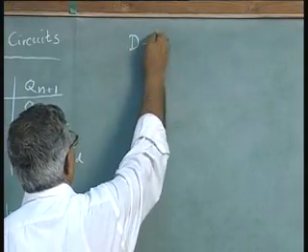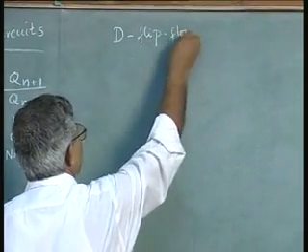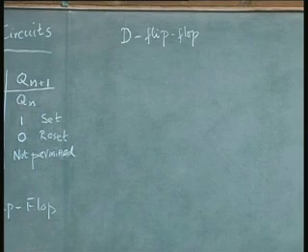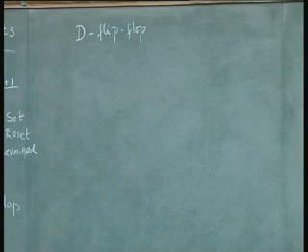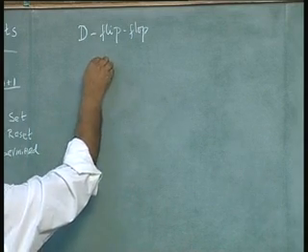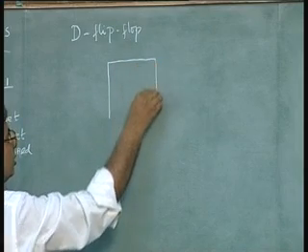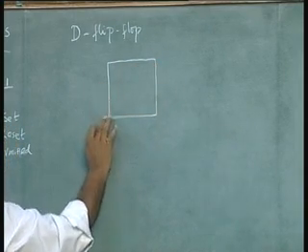We will call it a D flip flop because once we have already introduced the clock concept, we can continue to call all the other circuits flip flops. You will always have to mark a clock input. So, this clocked flip flop would be the same as the clocked SR flip flop,